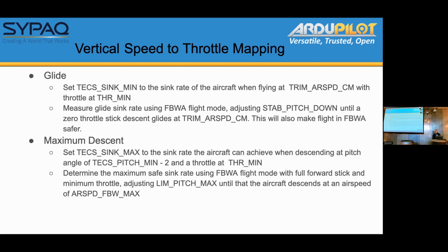We've got auto flaps, obviously, but it's not quite the same as the air brakes. What about negative throttle and stuff like that? Like for speed descent, do you include that into TECS as well? Okay, so the question is, what about negative throttle? I will talk about that, but yes, for maximum descent rate you can use the minimum throttle. It is usually set up for 0, but you can have a negative minimum throttle, and that enables you to achieve significantly higher descent rates.